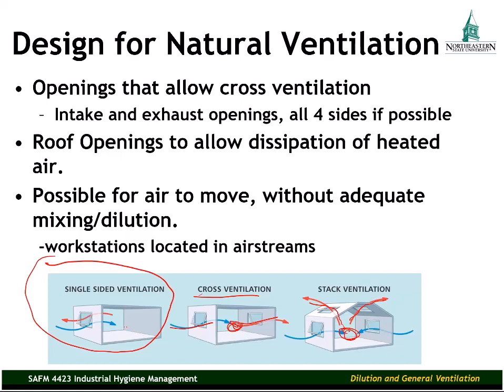Again, the single-sided ventilation, that's a little trickier. If all you had available to you was one window that you could open, you want to make sure to have continual monitoring going on within your space to make sure that adequate mixing and dilution is taking place. But really, that applies to all of these situations. Monitor your air continually.